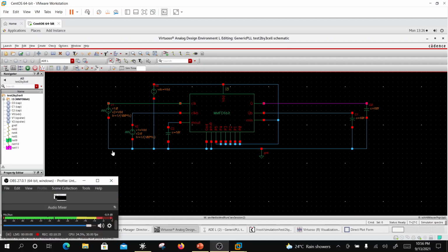So that's the multi-modulus frequency divider, operational up to 5.5 gigahertz, and the VCO will be driving that. So we will see that in the next circuit, and we will see the output stage of the PLL, which is 2 by 3, is up converted to F naught with a quadrature output. So that's what we are going to see.